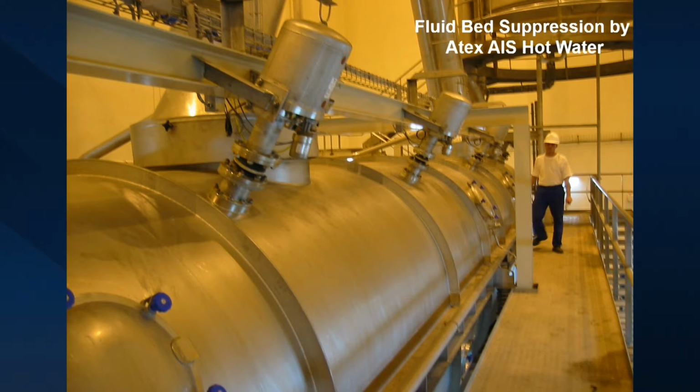Typically for explosion suppression, powder is used. And powder means so-called sodium bicarbonate, or most of you will know it as baking powder. So that means that nothing else but baking powder is pushed into the process. This will fall apart, it will form CO2, and when it falls apart, it consumes a lot of energy, and that is what makes our suppression.